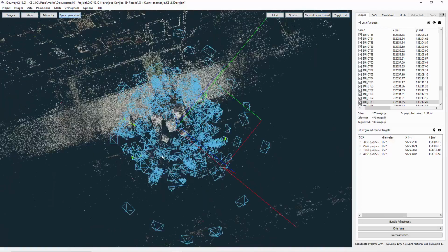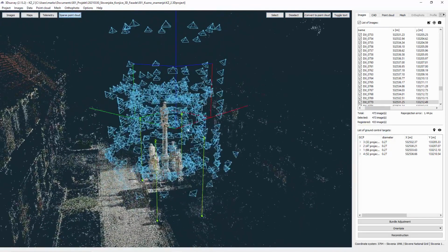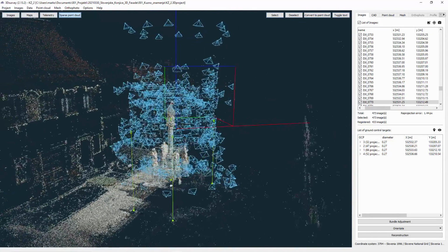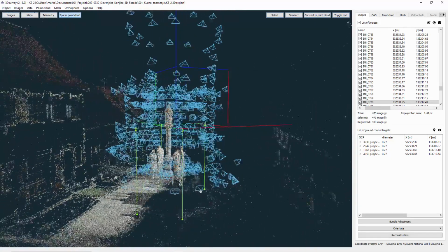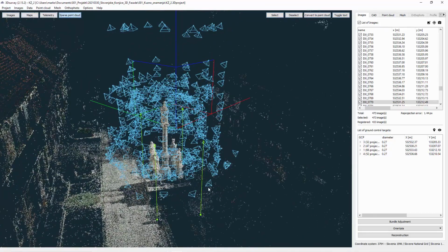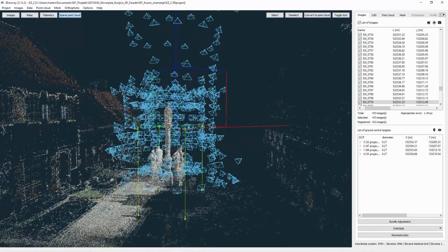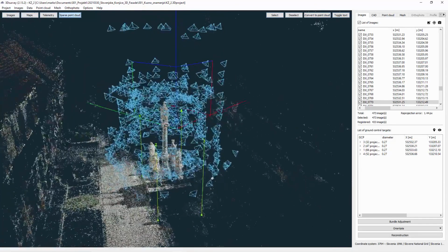And as you can see, I managed to fly really nice circles around the objects, and there are, let's say, 20 or 50 circles around it. And then at the end, additionally, hand shots with the same drone, so with the Phantom 4 RTK, I was holding the drone in the hand and added even more details to the lower parts, and of course also to the higher parts from the low perspective.